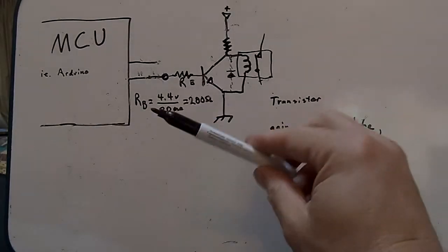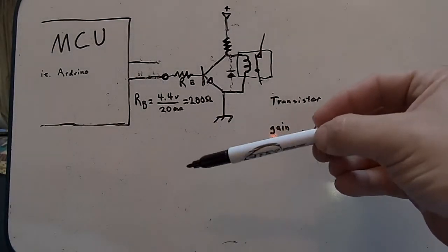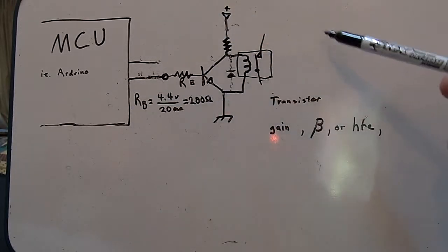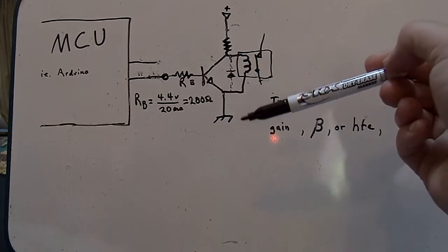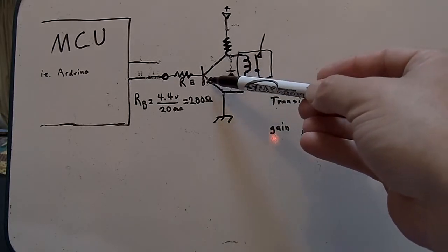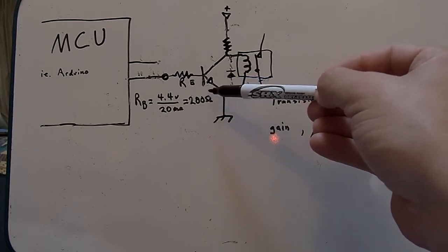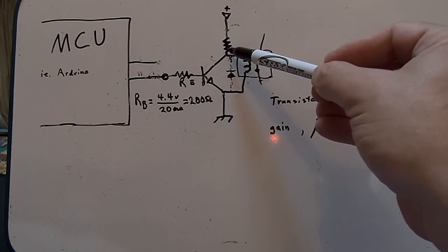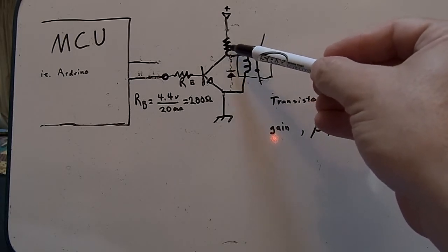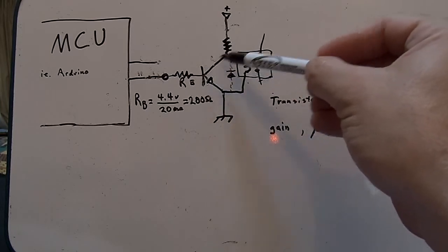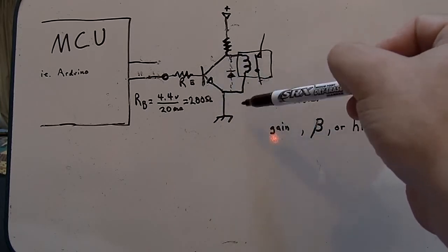Okay, so there's several ways you can go using transistors to amplify your current, to either invert your phase or don't invert your phase. This one I did invert the phase again, using an NPN transistor this time. So when this NPN transistor is turned on, it's going to pull this pull-up resistor down to look more like ground, and there won't be enough voltage left over to run this relay.